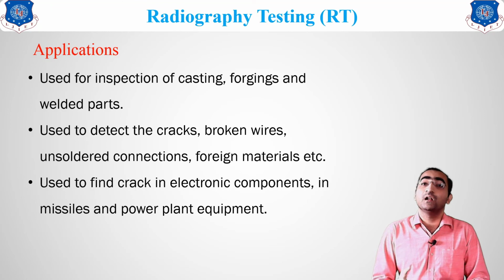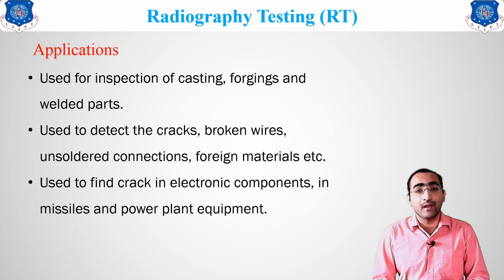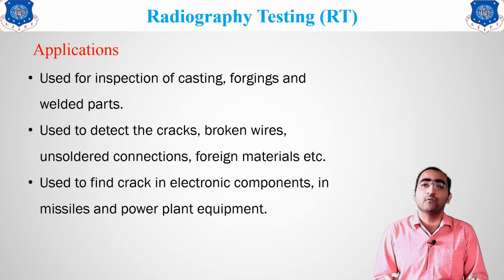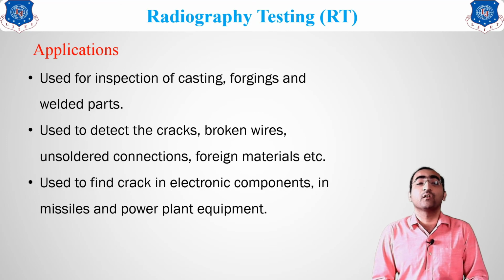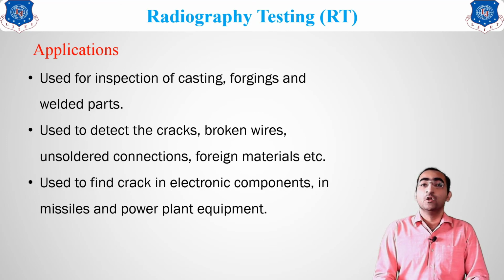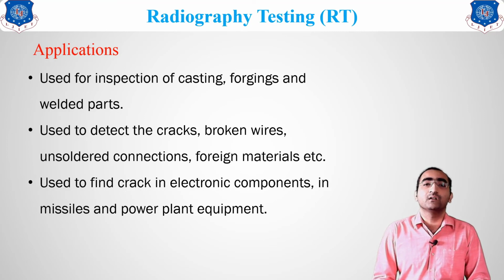Any ferrous material is tested with the help of magnetic particle testing, any surface defect with liquid penetrant, and if the sample is large or long, then we will go for the ultrasonic method. Clear? So this was all about the radiographic technique, and here it ends all of the non-destructive testing methods. We have discussed liquid penetrant, radiographic, ultrasonic, magnetic particle, and the last one, eddy current testing. So here it ends your unit, known as non-destructive testing. Clear? Now in the next lecture we will go for the new unit.